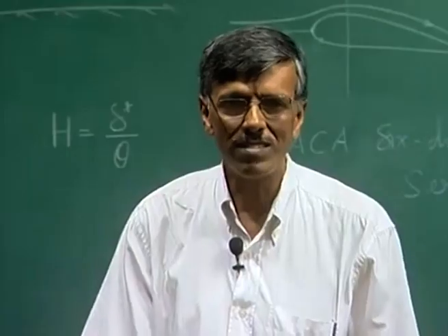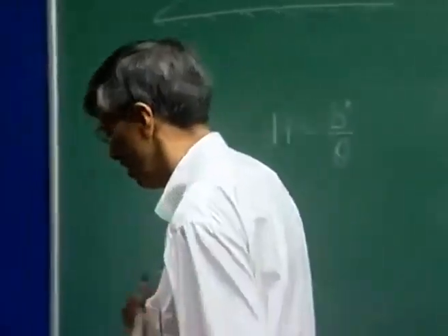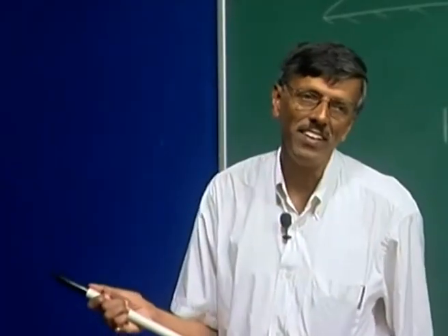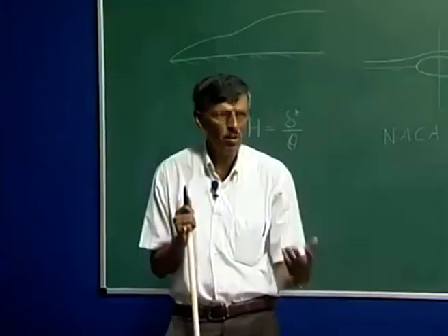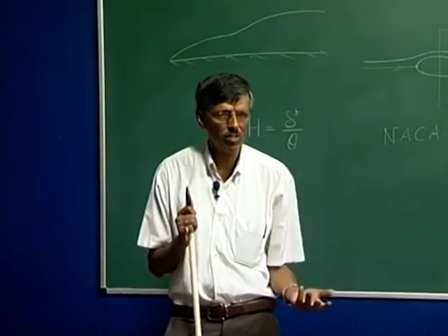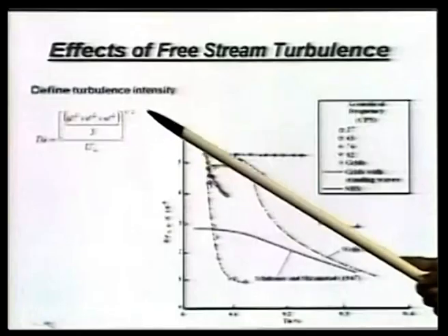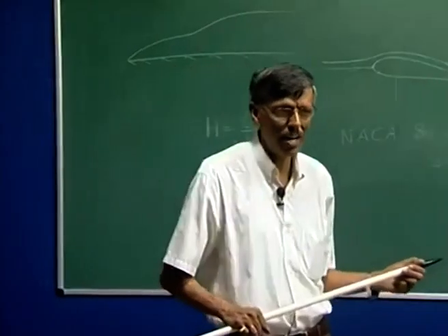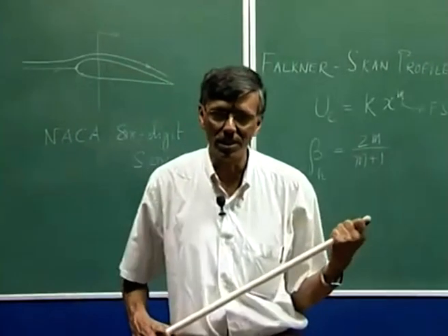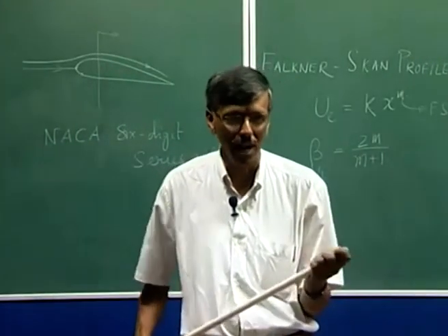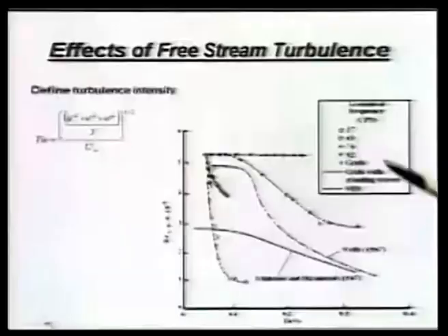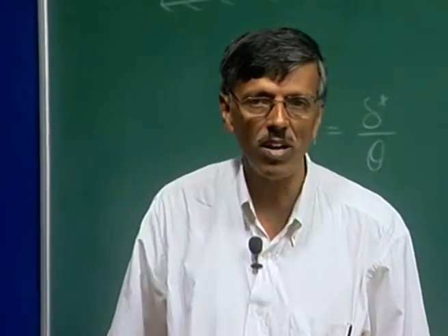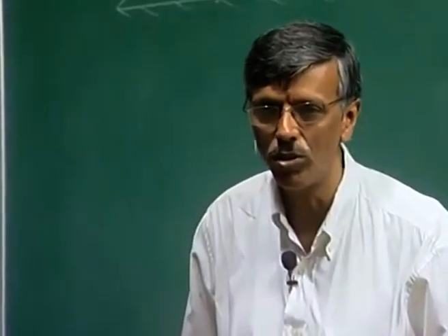So, it is quite unusual that people have depended so long to try to define a phenomenon of turbulence, which is essentially stochastic, in terms of a single moment. What is this moment? This is the second moment, right, the RMS value. What happens to other quantities? Of course, the mean is taken care of, that is what you calculate. Second moment is okay. What about the higher moments? This we will talk about, and we will show that it is very significant that you should not lose sight of this.